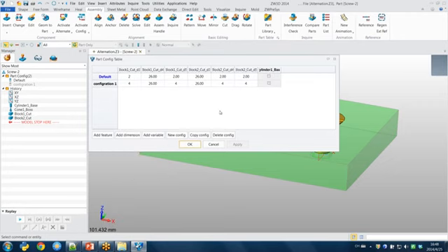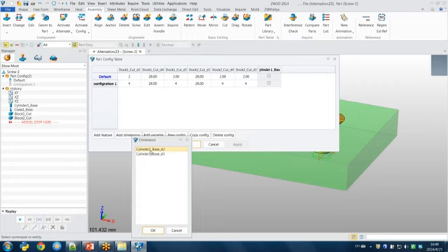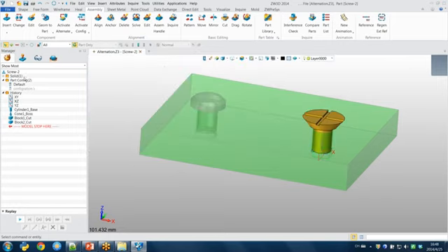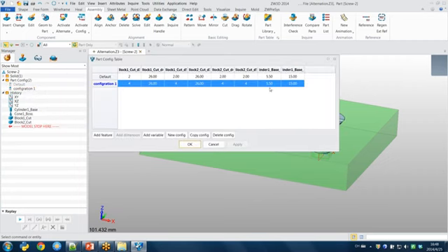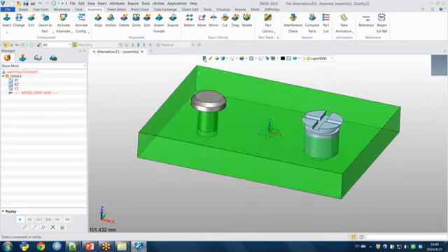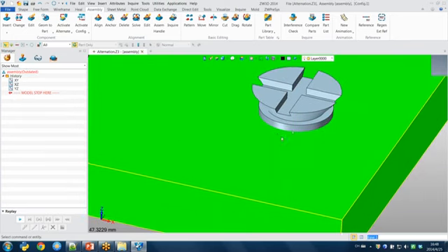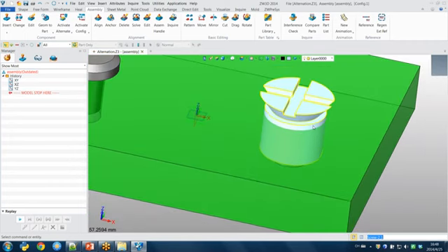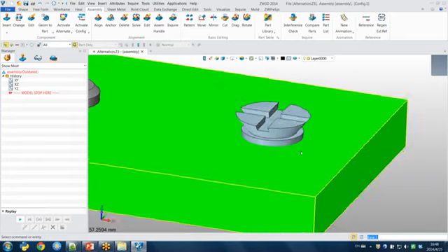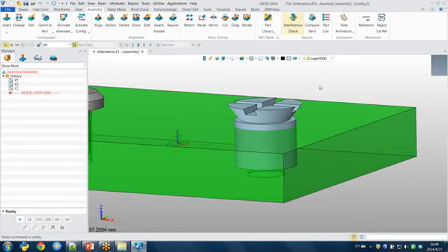Sketching. This one, add dimension. And press OK. Activate the component. Add it in the value. For example, if I change it bigger, press OK. So you can find it was changed. After I go back to the assembly, you can find there must be an interference here. Oh, there must be a gouge here.